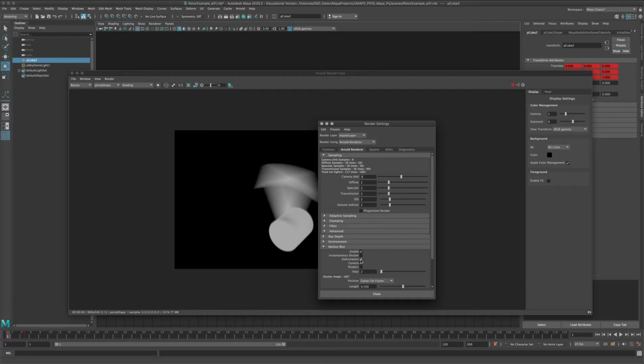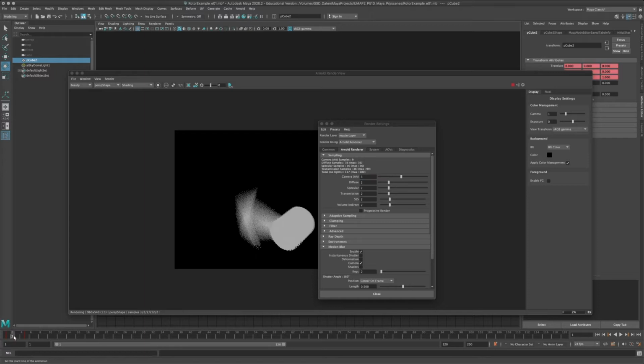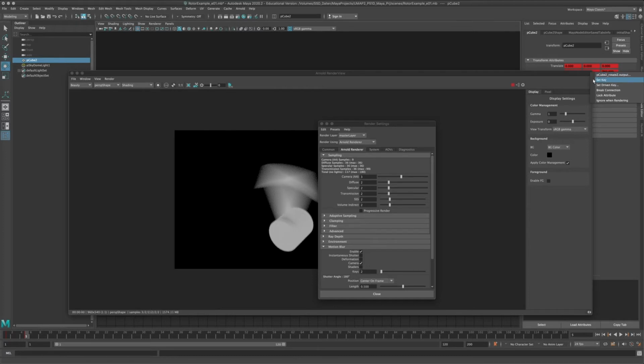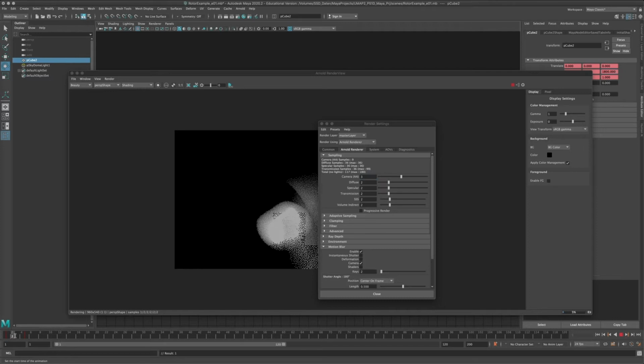And if there's a lot of polys in your scene and a lot of them are deforming, or even if not a lot of them are deforming, this might take longer than actually finishing your frame, at least if you're rendering on a GPU. So I turn that off if there's nothing deforming in the scene, so it's going to be a lot faster. So that motion blur looks okay-ish, but it's still not correct. But let's just change a few things here. So instead of 360 degrees, this is just going to turn 1080 degrees, for example. So I'm just going to enable motion blur again.